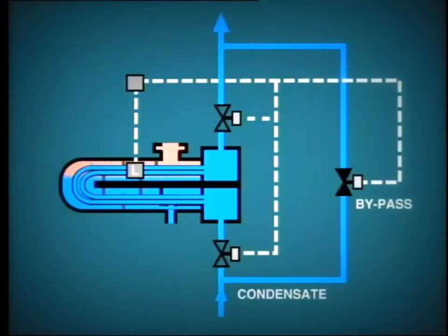In some installations, the high water level causes the condensate to bypass the heater altogether by automatically operating the motor-actuated isolating valves in the following sequence: open bypass valve and then close inlet and outlet valves. The matching of extraction steam flow to the heater and condensate flow through the heater takes care of itself automatically. As more condensate is pumped through the heater, more steam is condensed, so reducing pressure and pulling more steam from the turbine. In operating closed feedwater heaters, the operator must be sure to check that venting and drainage of the